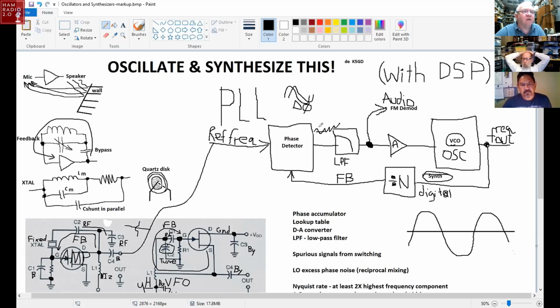That would change the DC coming out of the phase detector and feed it back to the voltage controlled oscillator, and then the output frequency changes. That's how you would set different FM frequencies. So instead of having just crystals like the first FM radios would have, the phase lock loop lets you set different digital division numbers, and you can change these during your operation to get different frequency outputs. That's a phase lock loop.